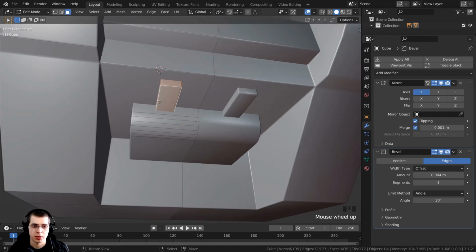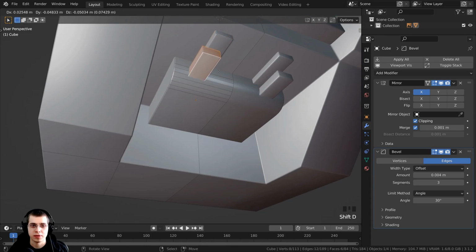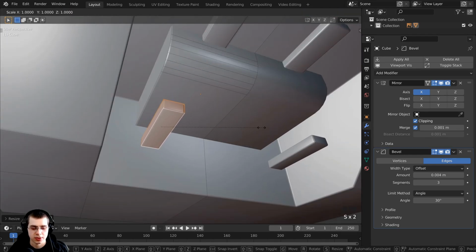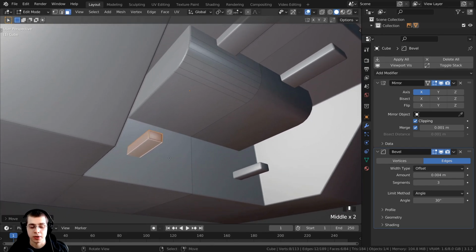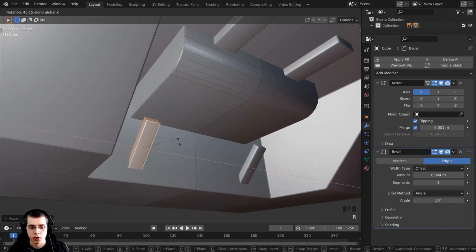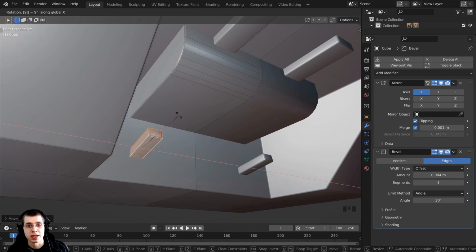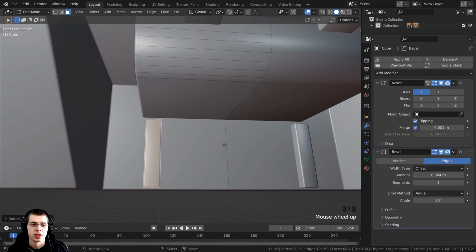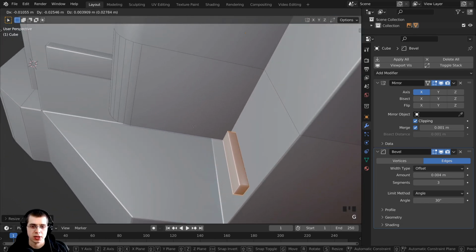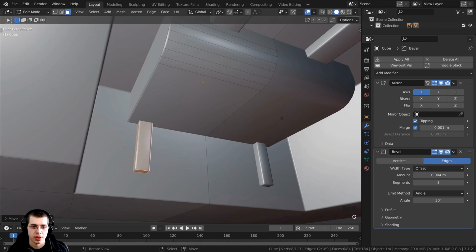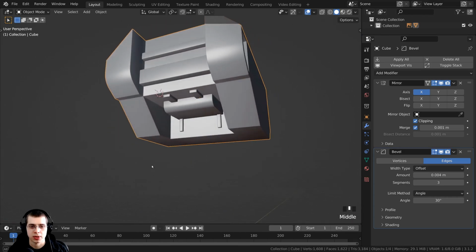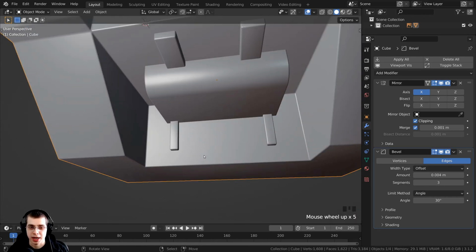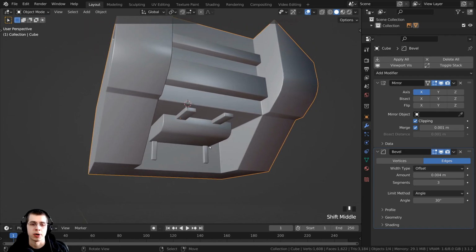All right, and then back in edit mode, just make sure you have this selected. I'm going to press Shift D to duplicate, and then S to scale. Let's also scale this down on the x-axis a bit, and then I want to bring it over here. And then I want to rotate it over, so I'm going to press R to rotate. Let's rotate it on the x-axis, and then I want to rotate it over exactly by 90 degrees, so I can type in 90, and then I can hit Enter. Let's press S to scale it down a little bit, and then G to grab, and let's just stick it right up there and bring it back a little bit. Just stick it in there. All right, tab to go back to object mode, so that's looking pretty good. So then right here, we are going to be adding a piece for the neck, but we will do that in the next part of the tutorial.